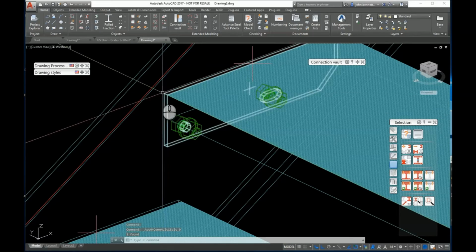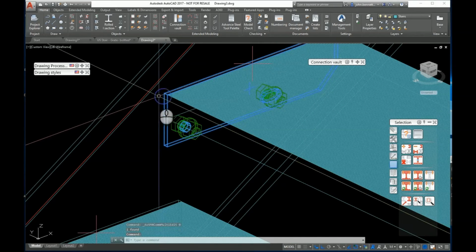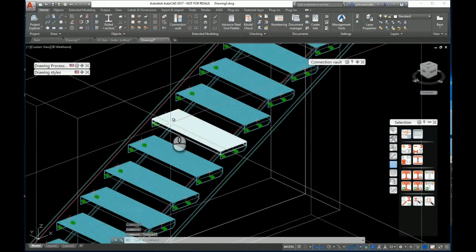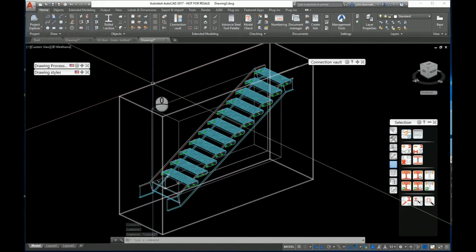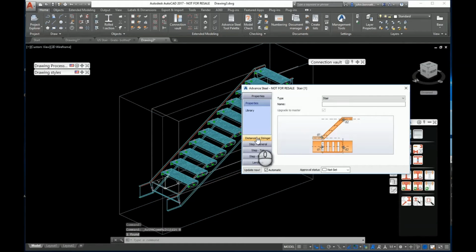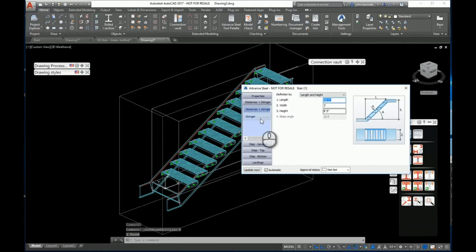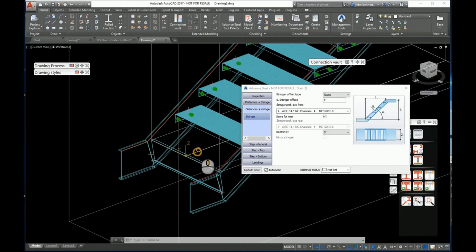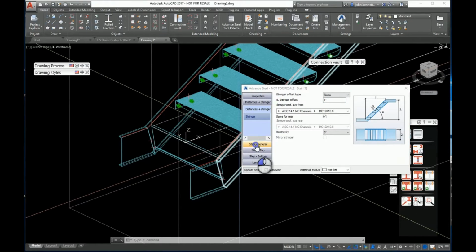And what I was trying to adjust is this distance from the edge of this plate to the edge of this channel. So if I just go back into the macro, to get back into the macro, just double left click with your mouse on the joint box around the edge of it, and it'll take you back into the macro. So I changed that offset in there to 1 inch. So now we want to go back through that.